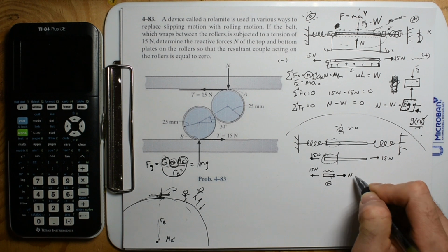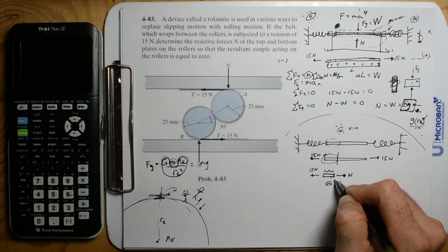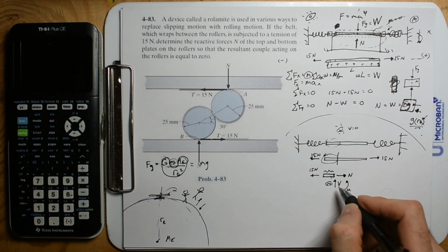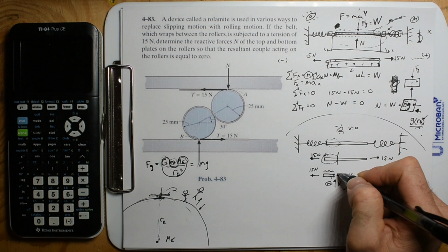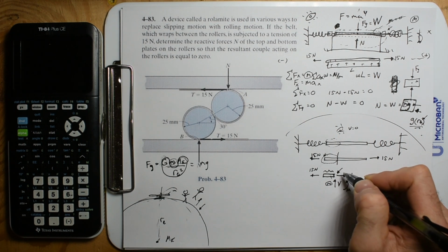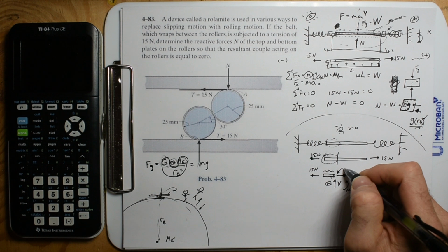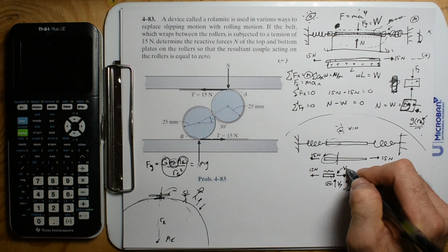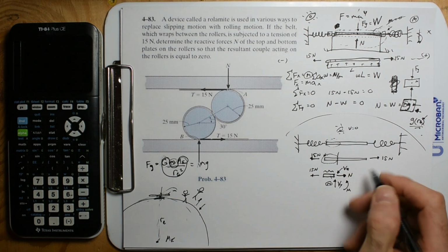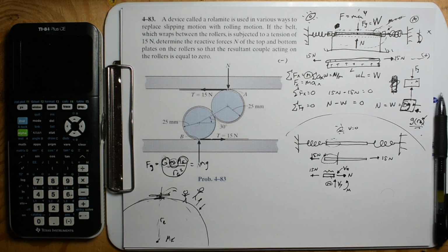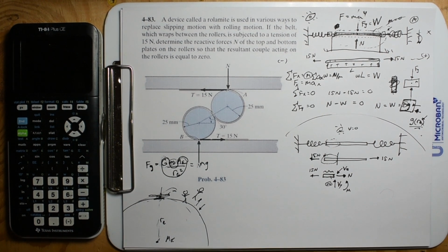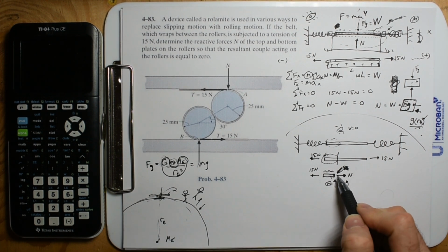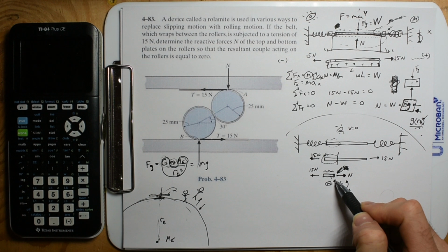So anywhere where you cut, like right there as we made our cut, hell yeah, sky's the limit. You can have a normal force, you can have a shear force, and you could have a moment. Besides the normal force, you could have a shear force in two other directions. So you could have a shear in the Y, and then a shear in the Z, and then the moments. This could be moments in 3 directions as well. But for two-dimensional stuff, just to get the hang of it, we chop that rope, we could have a normal force, and we could have a shear force.